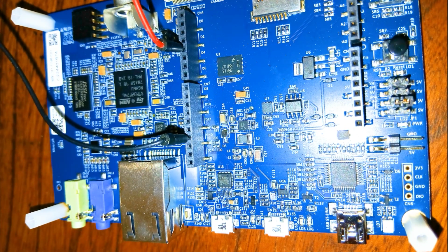Before uploading the code to our microcontroller, we need to prepare the circuit and hardware. To do that, pin D4 of the Discovery Board must be connected to anode of the LED. This is done via the red jumper wire, which is shown in the picture, and the GND pin of the Discovery Board must be connected to cathode of the LED. It is done via a black jumper wire, which is shown in the picture.